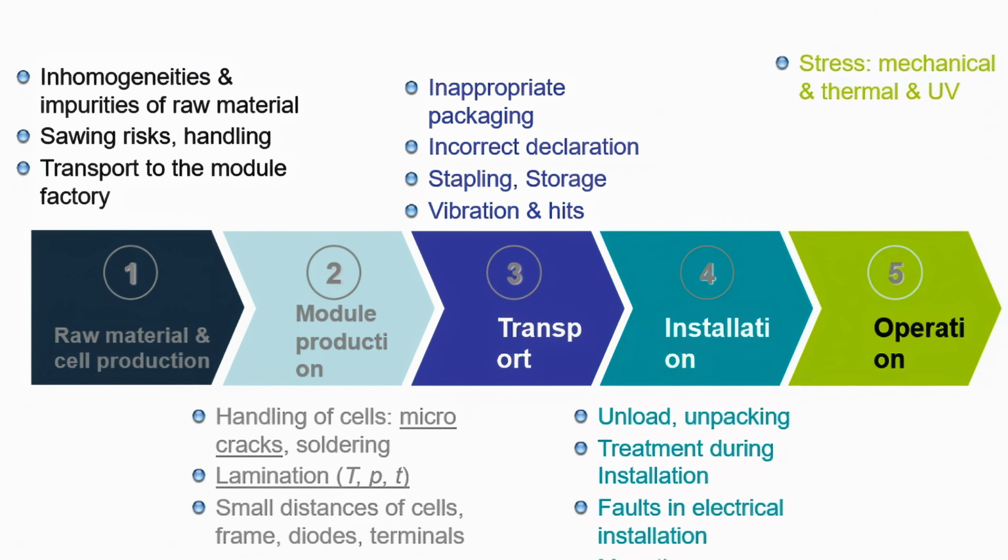And mounting also could be an issue if the mounting foundation is not really fitting to the modules and so on. If they put it into the installation frames or the foundation with high mechanical pressure and so on, it could lead to some damage of the PV modules.